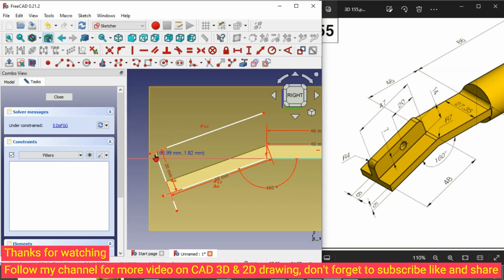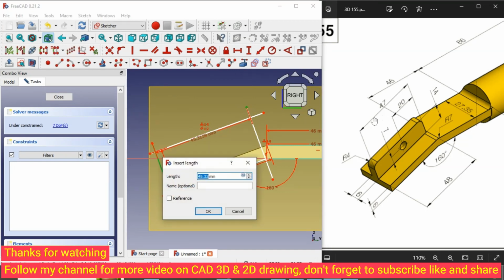So drag this line a little bit longer, then draw another line here, set it perpendicular to this line. Then we set the distance from here to this line is 47.